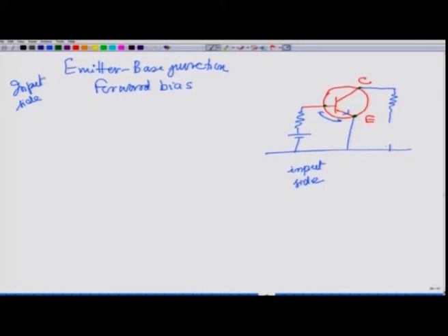To make it reverse bias, what do I do? Remember, it is NPN. So, this is N, this is P, this is N here, and now I am talking of this PN junction here, and this should be reverse biased. I am not connecting the battery at the base, I am connecting this battery at the emitter end here.